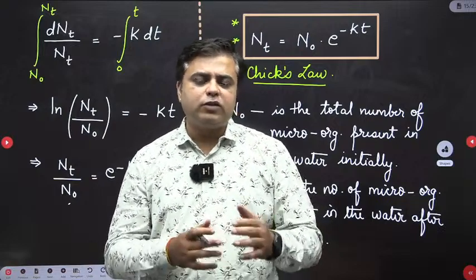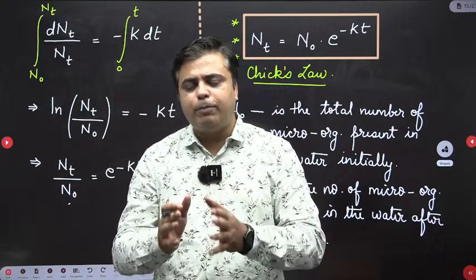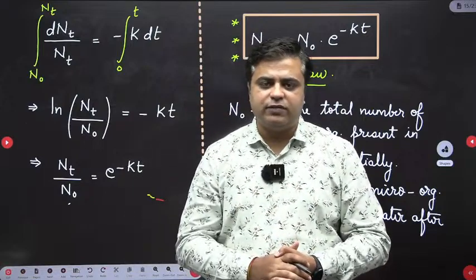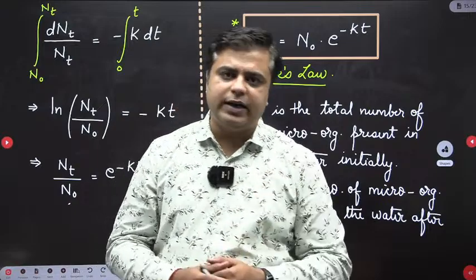That's why the pH of the water sample is maintained in the range of 5 to 7, so that HOCl predominates in the system and it gives the maximum efficiency of disinfection. Combined form of chlorine actually takes care of the future recontamination.